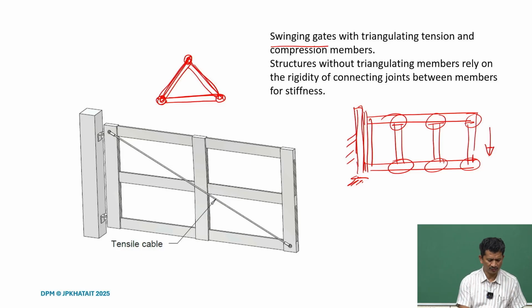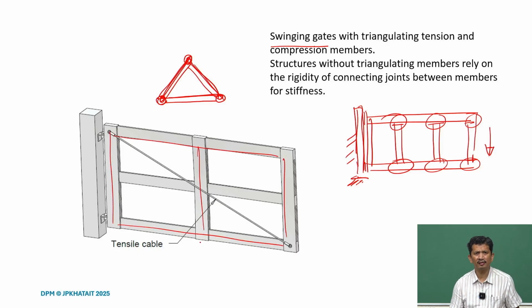So, in this case, this is the parallel structure you have. If you do not have the triangle in place, no matter how many members you put, actually in a way it will be worse, because you are simply adding weight without constraining that movement. There is no way to constrain this movement, there is always a degree of freedom. So, that will not solve it.